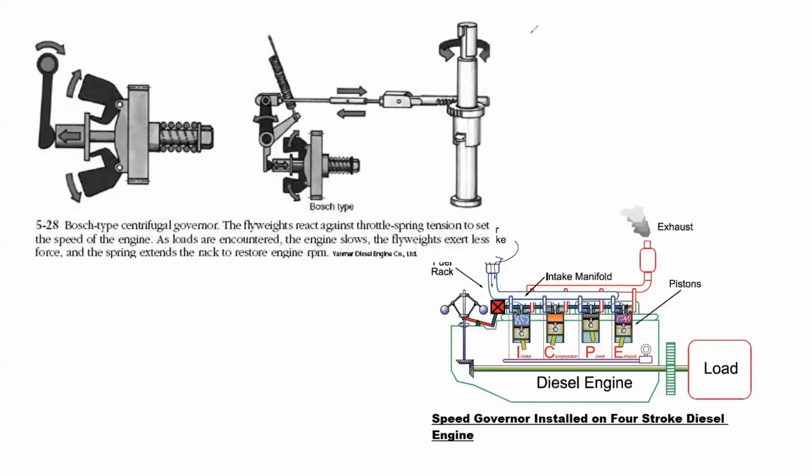So the basic governor attachment is shown here, right? If you can see here, this is your plunger, and this is the accelerator. Oh, this is the fuel control rod. The fuel control rod is here, then it is attached to a governor. This is the governor, and this one rotates. When the speed increases, these two weights tend to move outward.